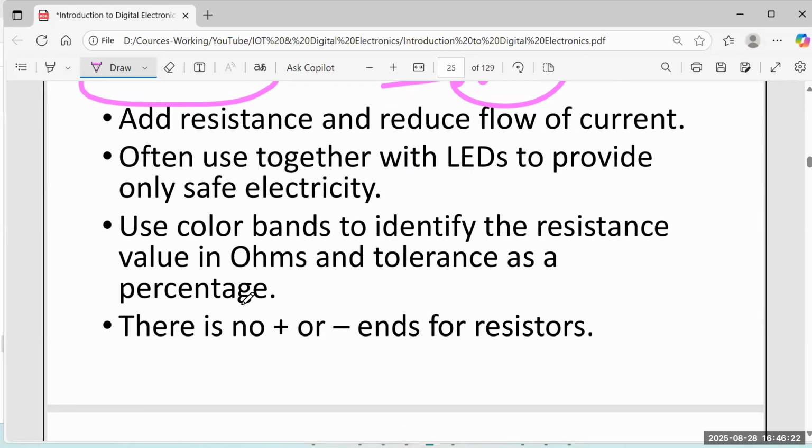Right. So resistance is measured in ohms. Right? So resistors resist the current. Thereby, whenever you introduce a resistor, it limits the current, reduces the current. If you want to further reduce the current, add higher resistance. Rather than 220 ohm, add 1 kilo ohm, or add two resistors in series. So then 220 plus 220, 440 ohm.